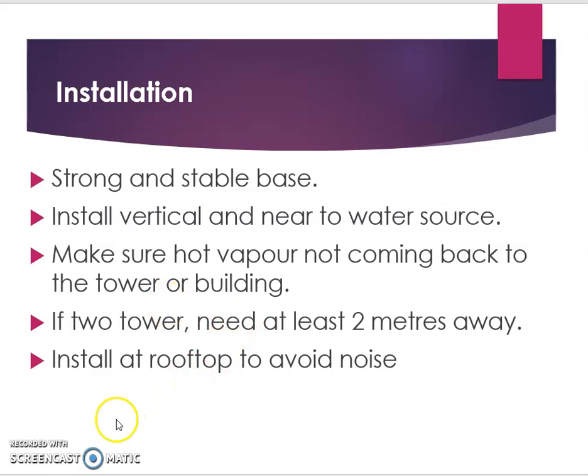The next one is that we should install the cooling tower on the rooftop or far away from the building to avoid noise, because the noise from the fan and the motor of the cooling tower is quite loud, and the droplets of the water will make some noise, and maybe it will disturb the occupants of the building.